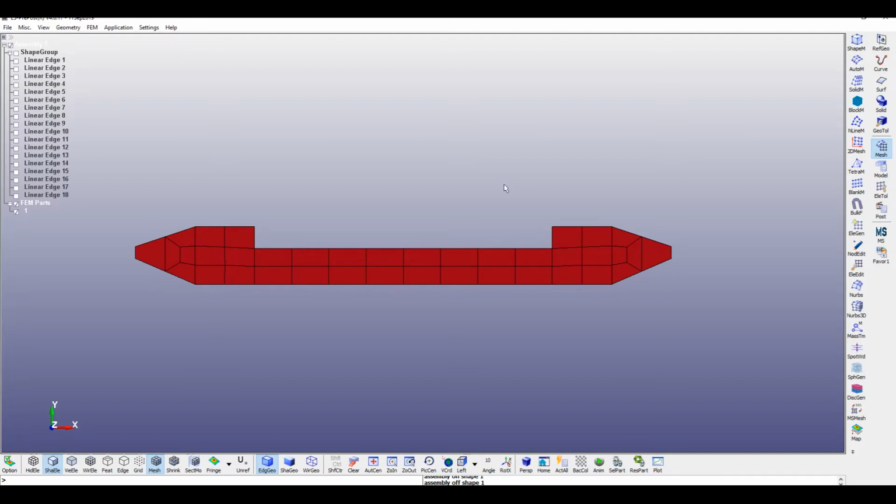And then we need to merge the duplicate nodes, because if the same edge is selected for generating a mesh, the common edge will generate two duplicate nodes at the same point. Due to this reason, duplicated nodes should be merged. We need to do this with the element tools options.